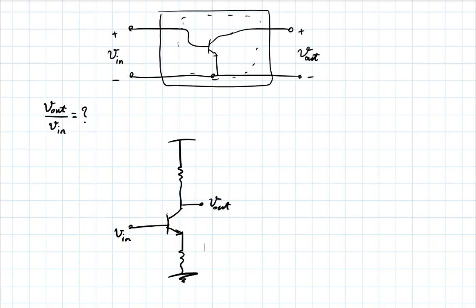Exponential, right? How about the FET? It's quadratic, right? It had, in its active mode, which we call saturation for the FET, it's VGS minus VT squared, right? So these are not linear devices. Now, if you're dealing with nonlinear devices, in general, speaking about a constant ratio could become problematic, okay? And that goes to the core of what we are going to discuss now.